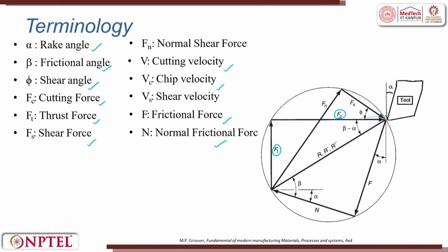So, now what is the other thing which is not known is the shear velocity. Shear velocity is the velocity with which the shear plane is moving, and it is called Vs. Now, with this we will try to form an interlink such that we can try to calculate the cutting force.